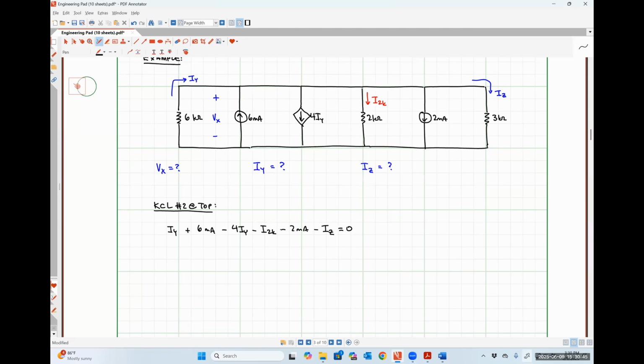So when everything is in parallel like we have here, the best piece of information that we could find would be the value of the voltage, Vx. Because as we learned in Engineering 120, and as we can prove using Kirchhoff's voltage law, whenever we have things that are connected in parallel, they all have to have the same voltage drop across them, okay?